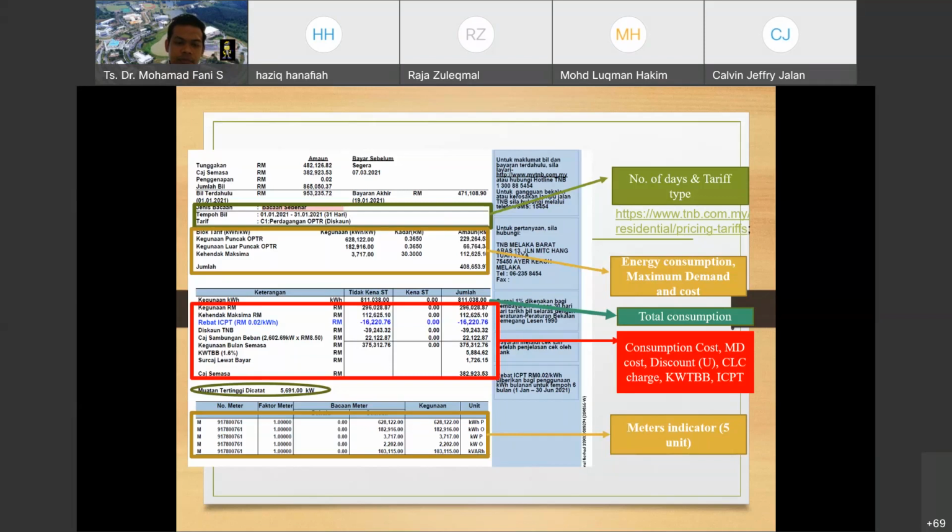Is about 5,600. So what's the difference between maximum demand and the peak, the highest load recorded? The peak demand is the peak power consumption. The difference is that for maximum demand we consider the largest power over 30 minutes, not the peak one.